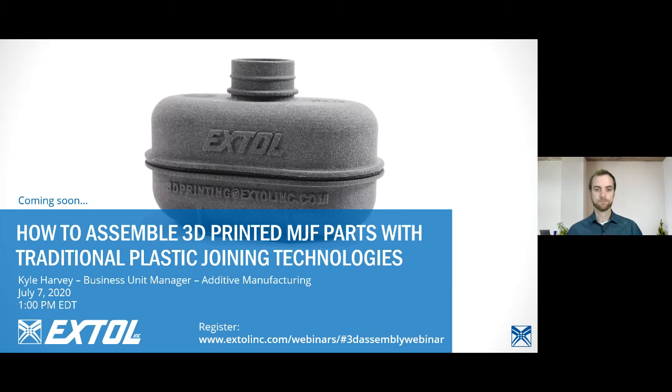Okay. Another one here, and this one is, how do you assemble the two parts together, or how do you attach the caps to the PA12 supports beneath? Yeah, so that's application specific. In the use case, we had a threaded hole that we just used a flathead screw to physically attach those two together.